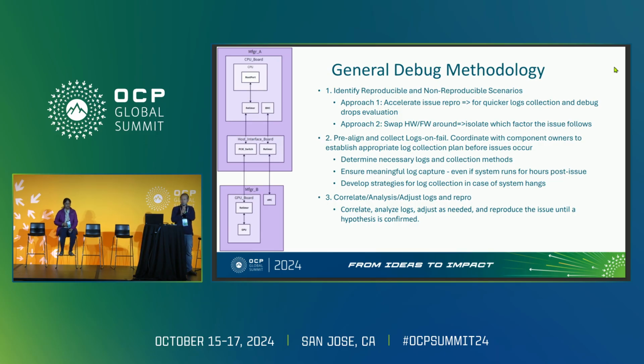So, here I shared some practice of our current shipping products. You can see from the diagram, it's a heavy complex PCIe connection there on the AI GPU system. From the CPU, through the retimer to the host interface board. And there you'll find the PCIe switch and connect it all the way down to the GPU baseboard. And there you have another retimer. And then finally, through this long pole path, you reach the GPU.